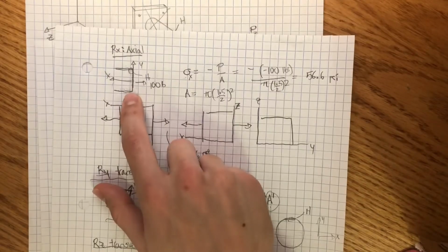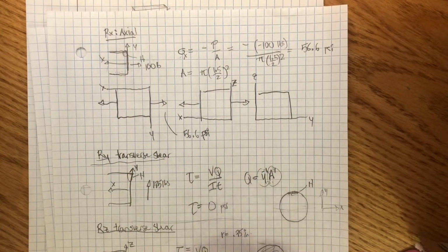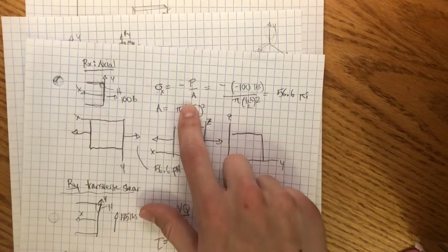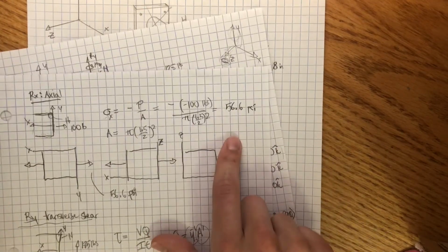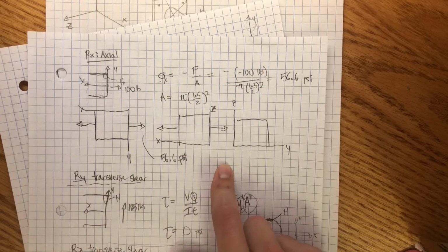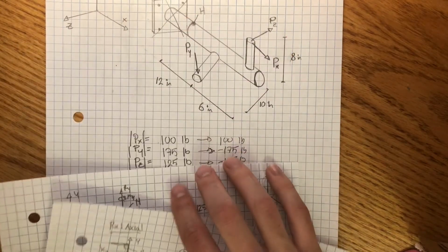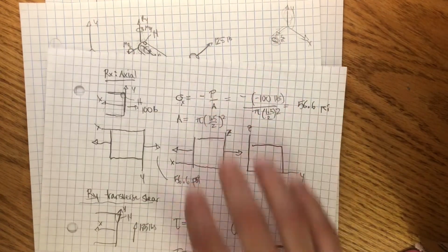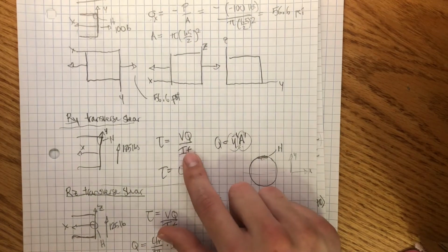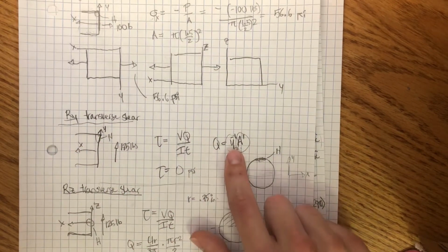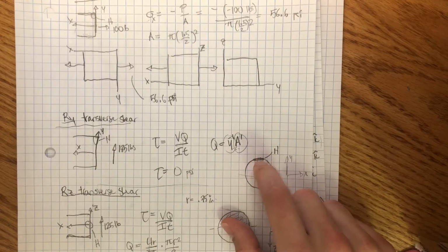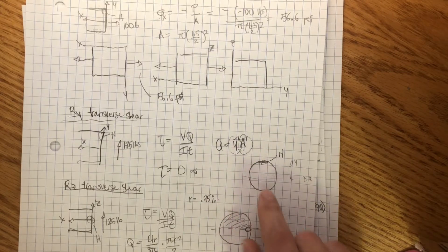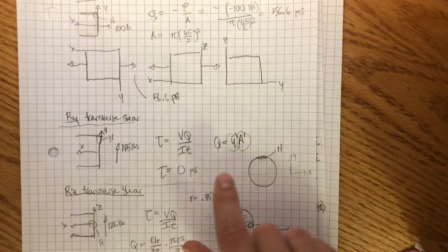So Rx, we knew that it was in the axial direction because of the way it went along the x-axis. And we knew that it was going to be tension, so we did negative P over A. And this is what we got. So we added that to our stress blocks. Then we looked at the transverse shear forces that are applied to this, these ones that are perpendicular to the length of the tube. For those, we had to use VQ over It. But for Ry, we knew that H was in fact at the very top of the cross-section, which means that there is no outer area for H, and there is no Y as a result either. So we knew that tau was 0 as a result of that.